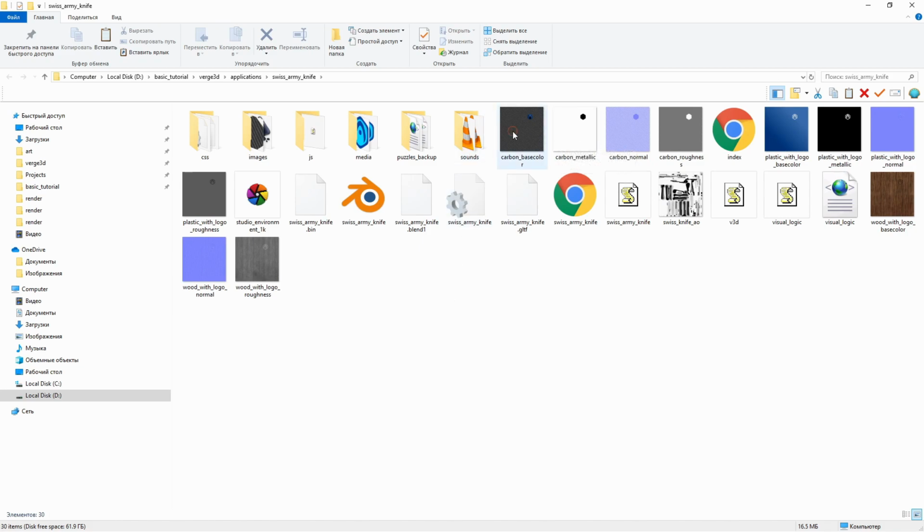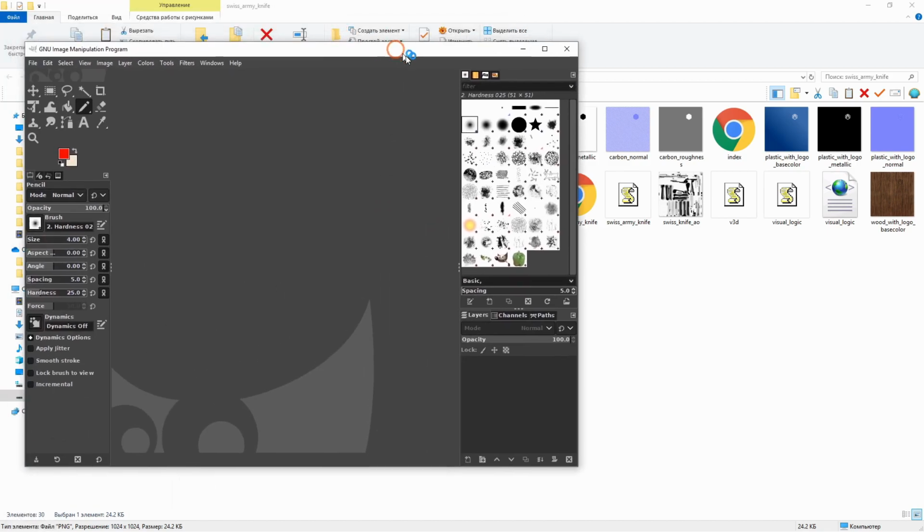As you can see, all the images are in PNG format. It is possible to resave at least some of them to JPEG format to save the file size and speed up the loading. Moreover, some of the textures are black and white, and thus we can pack them into the channels of a single texture. It might free some video memory and further speed up the loading.